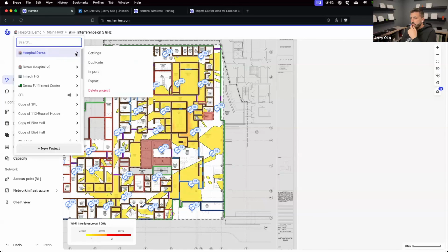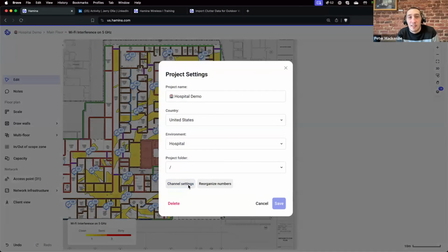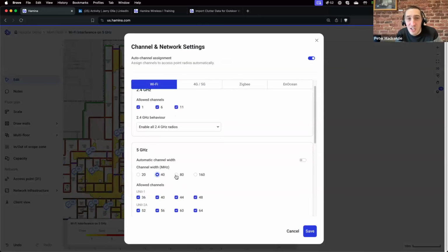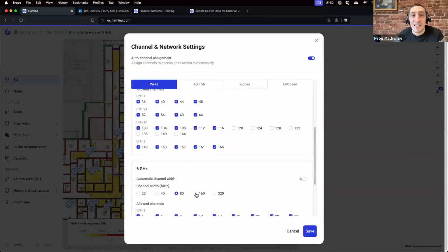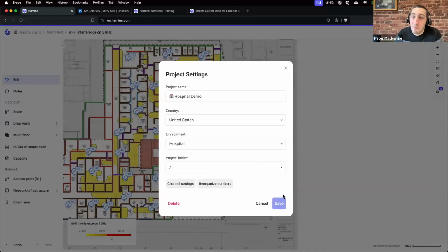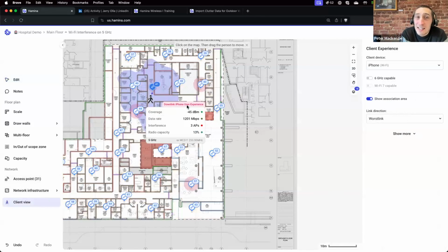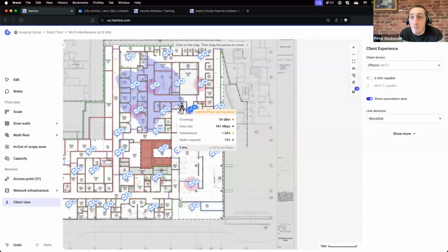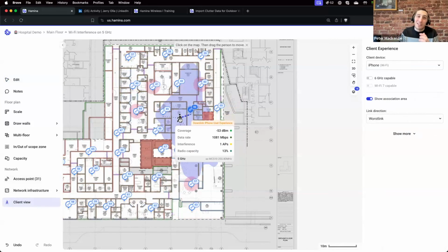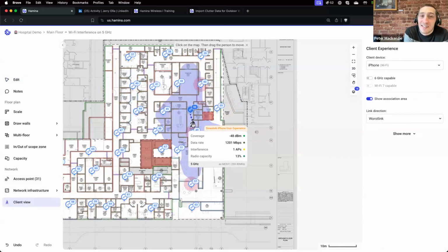It is definitely co-channel, and this is why I don't call it interference, contention isn't always bad. In some environments, you might go, actually, I'll accept some, because having the higher data rates will ultimately give me overall better performance. And it is a balancing act. You never want lots of it, but sometimes accepting a little bit is okay.